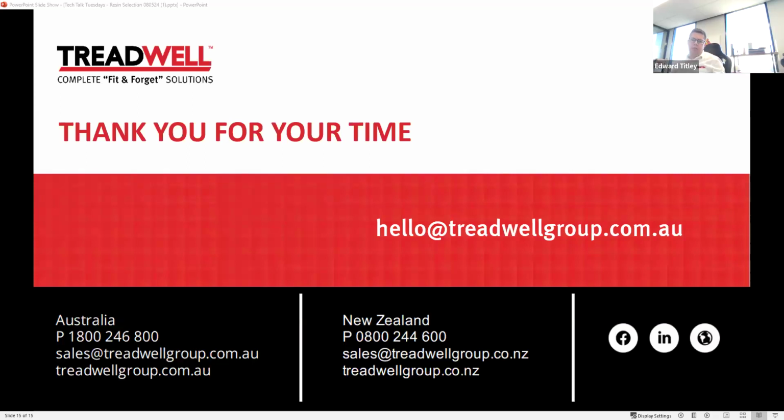In relation to another question from Max, polyester resin on the last slide. So the isophthalic resin, or the I series product, is a polyester resin. Phenolic is a different animal altogether, and I haven't discussed that in these charts. If you're needing to use phenolic from a fire performance perspective, I'd take that discussion up on a case-by-case basis. But on the last slide, polyester resin is I series, and vinyl ester is obviously V series. Hope that makes sense.